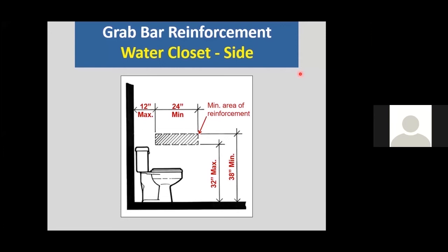Reinforcing for bathtub seats is not required under this law at all. Any other shower, or if there's more than a shower in the unit, then that seat reinforcement requirement goes away. So we're looking at surrounding toilets, the wall surround of bathtubs, and the wall surround of showers.